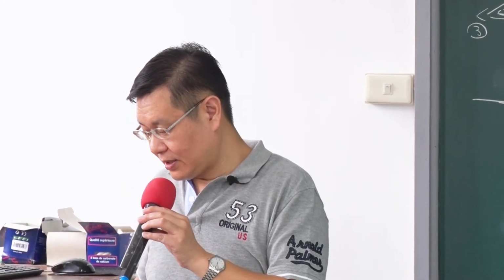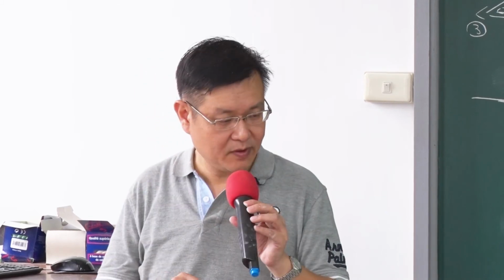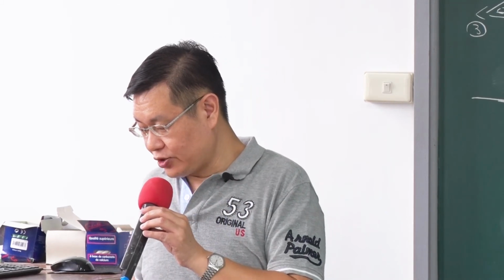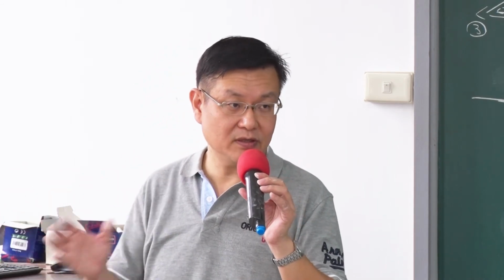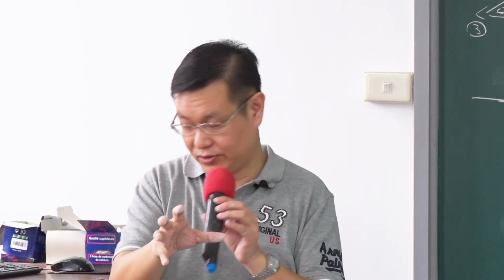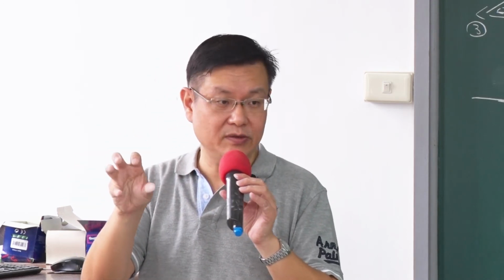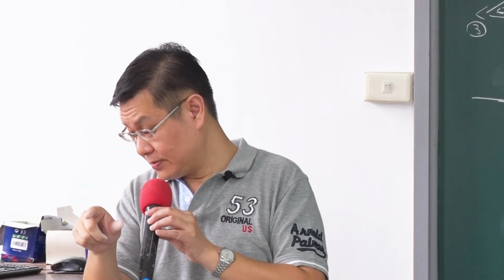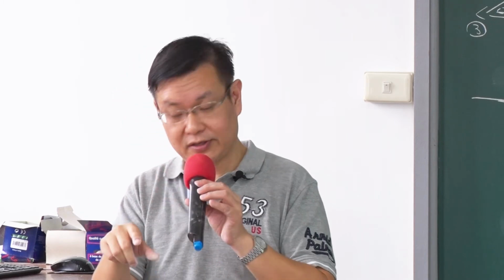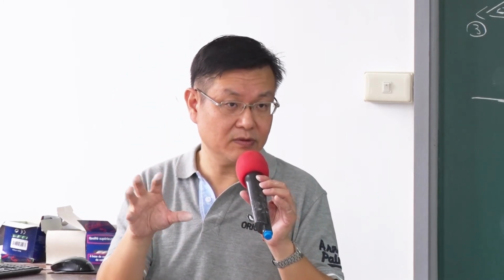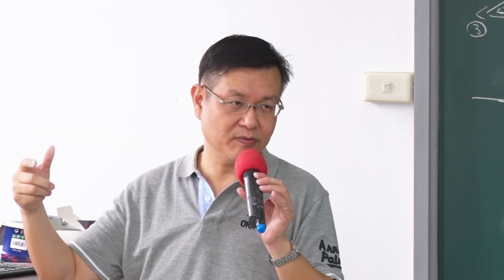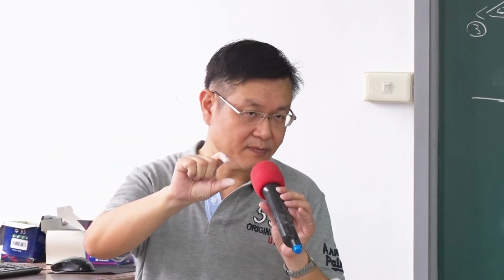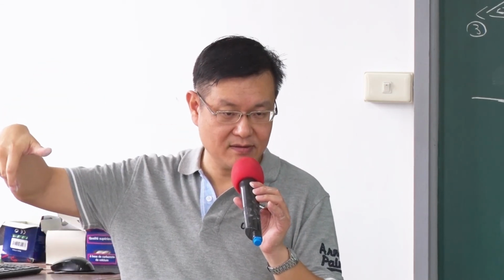Okay, so I encourage you to follow my instruction and try to group this kind of equation into 3 important groups, including the input parameter like the voltage. The second one will be the material property, like the G, the gauge factor, the Young's modulus, and also the resistivity, so you put these 2 together. And in the third group, you will have 2 different kinds of subgroup. One is the thickness, the other one is the width and the length.